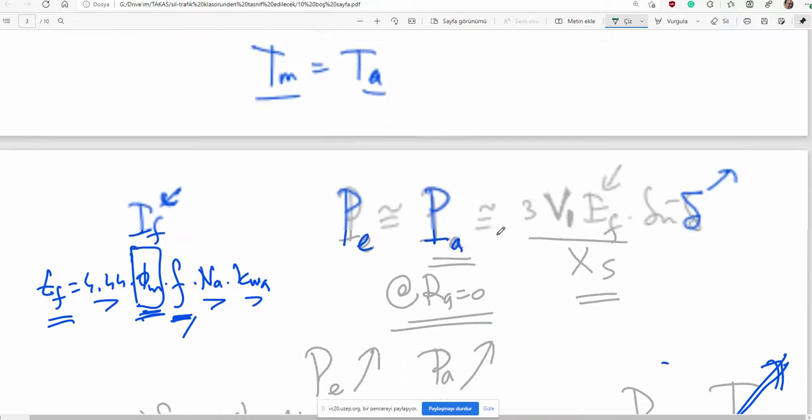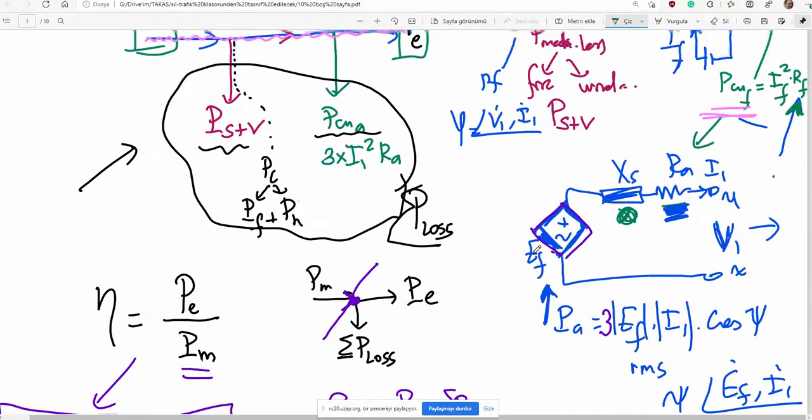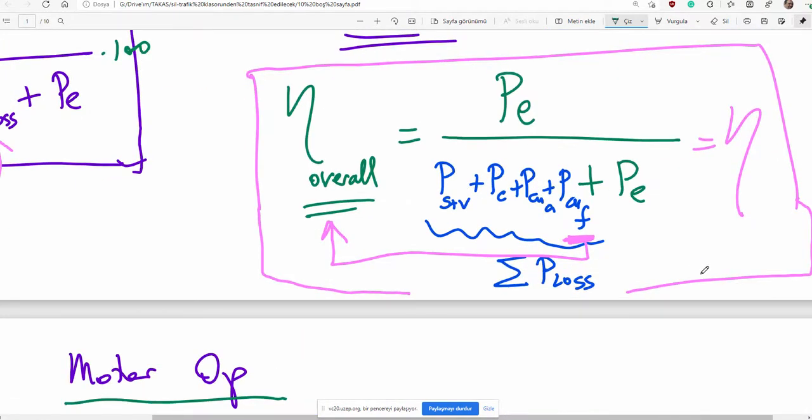Okay, again, come back to the efficiency equation. I have just remembered something. Here's the efficiency equation. Generally, those kinds of mechanical losses depend on speed. So, since speed is constant, that is constant. Again, frequency is constant, and EMF will change, of course.